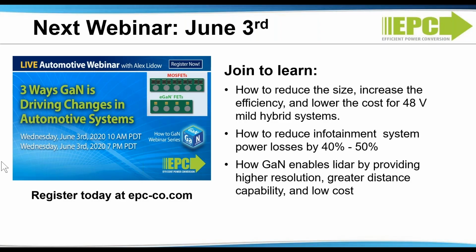And therefore the corner frequency is much higher. So lower inductance has a higher corner frequency and therefore much faster response capability. So in essence, as long as your controller can keep up with it, the transient response of the multi-level is related to the frequency of the inductor, which is twice the frequency of the buck converter without the multi-level.